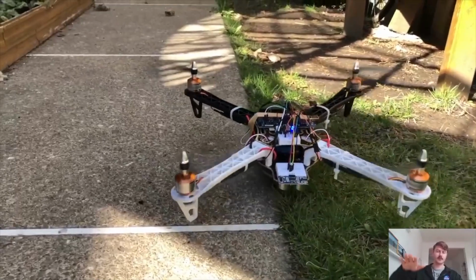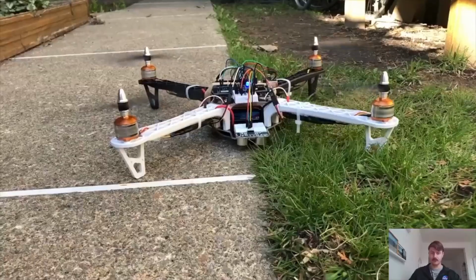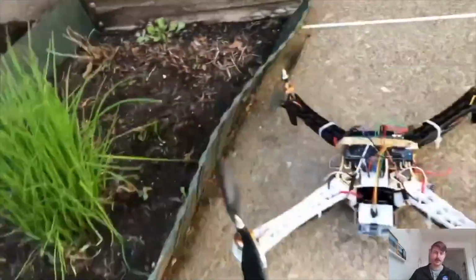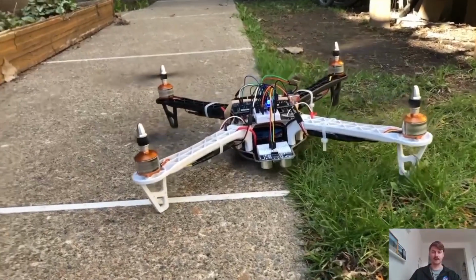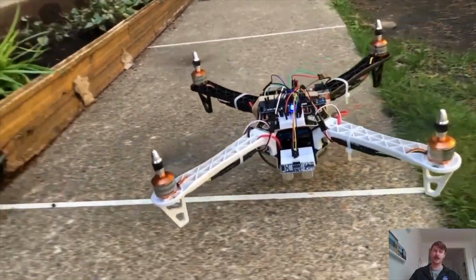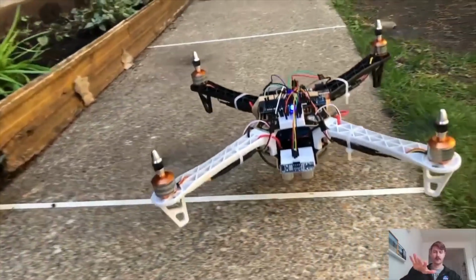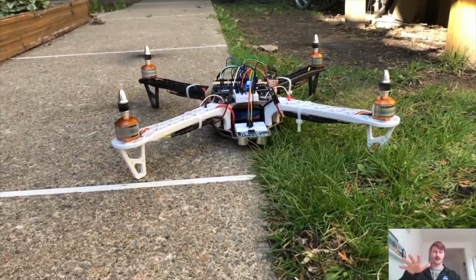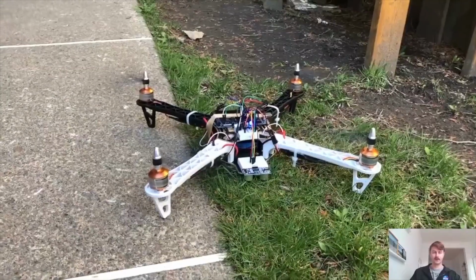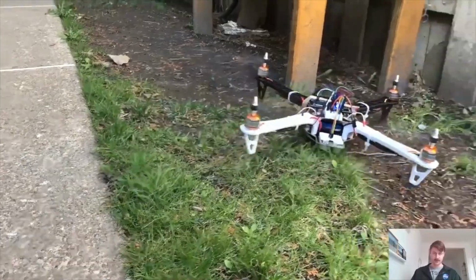The one issue is that the trim is off, so it's drifting forward. So that was tried to be corrected. So I went back and programmed the trim again because there's the little calibration that's programmed into the accelerometer. And now it was too far to the right, so it drifted to the right. But again, in the slow-mo, you see that there are active corrections being made to the position, and so the stability algorithm is running.